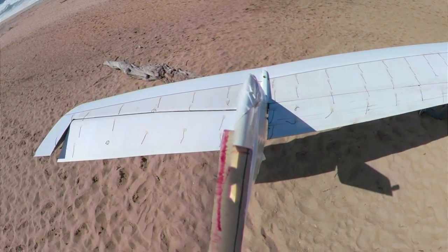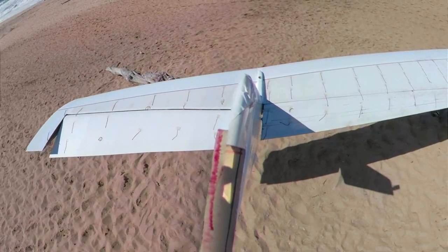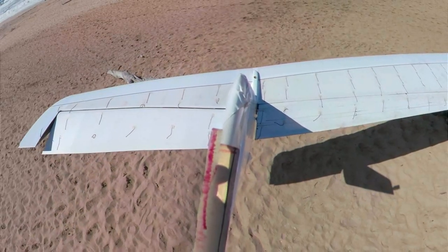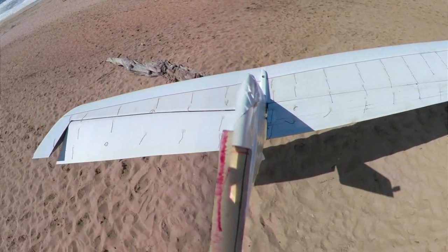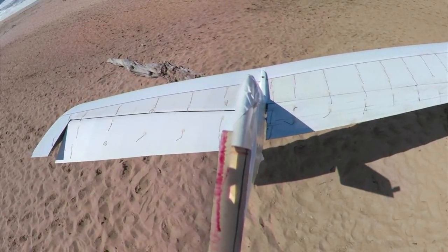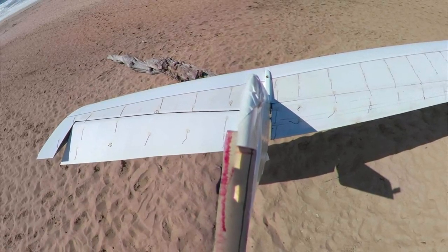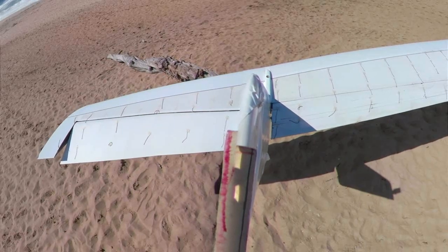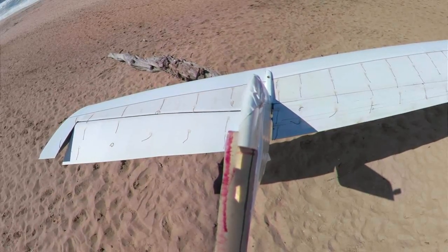In a little bit here, I think I do a little ground run, and with these ground runs, I tried doing some rolls. I would roll it to the right and see how much control I had over it, and rapidly discovered that I get this massive adverse yaw when that flow goes spanwise and separates, to the point where you can't handle the glider on the ground.